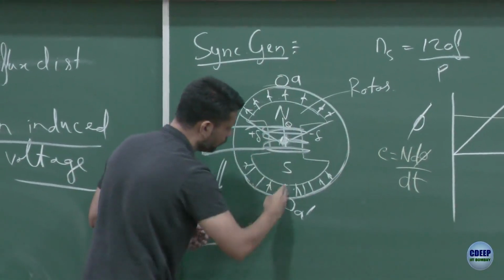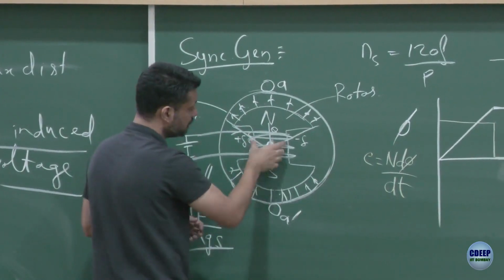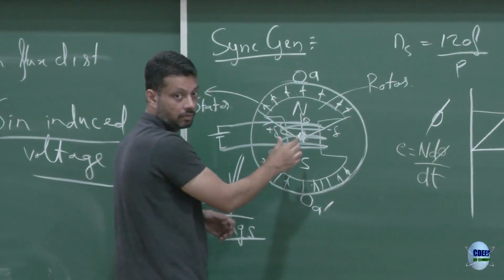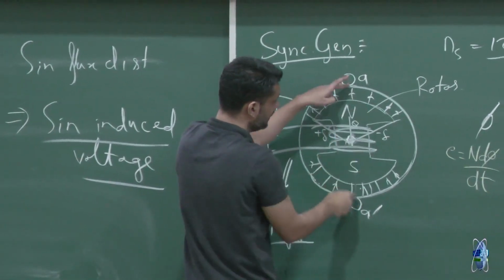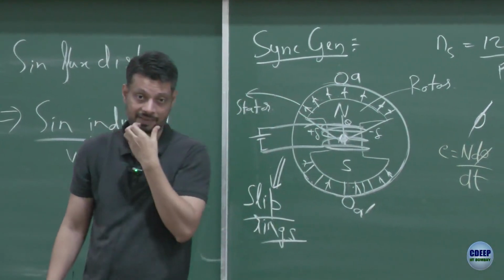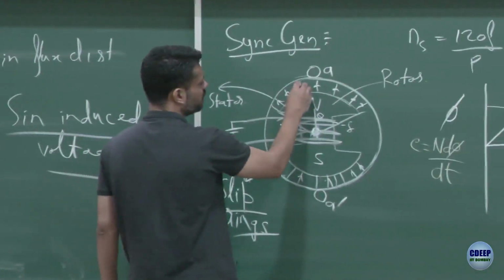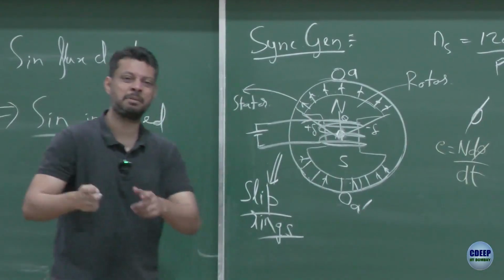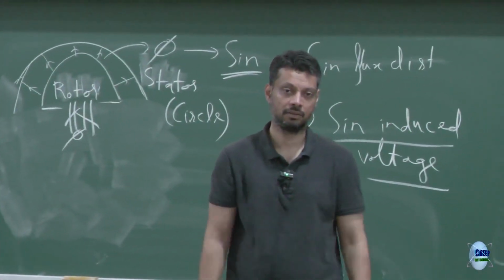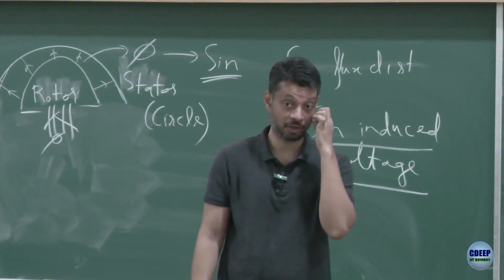This is the coil. So how much net flux is crossing depends on what flows through this part, right? If you take these 2 points, it's the flux crossing this which matters. Lines would most likely be normal because that's the minimum reluctance path. Lines would most likely try to take the shortest path. You don't have to take the cosine component.